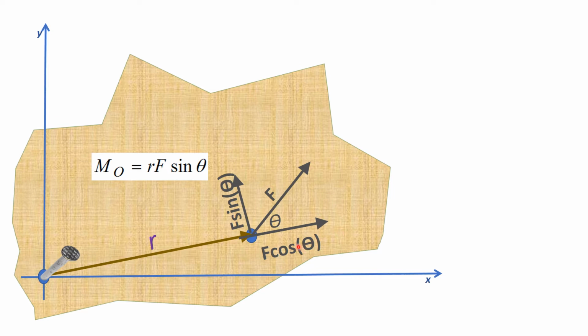That's just tugging on the nail. The piece of the force that's going to rotate it is this perpendicular chunk. That's opposite of that angle, so that's the sine of it. So R F sine theta, this will get R, and then F sine theta is the chunk that's going to rotate it. That's the piece of the force that does all the work here.